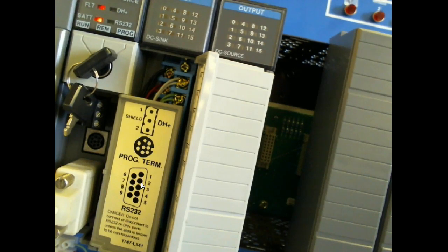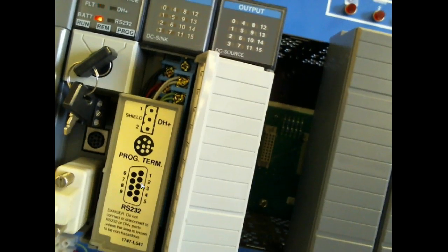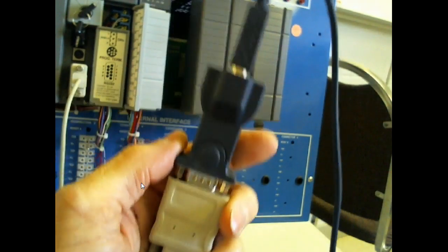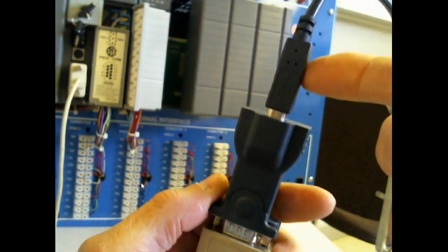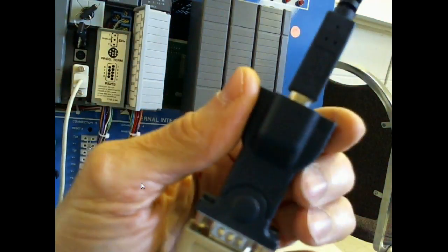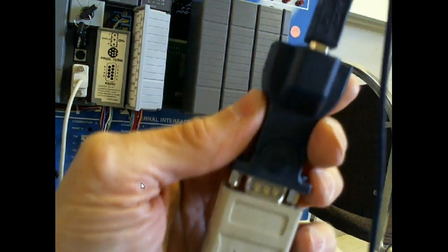Our computers no longer support it, but our serial interface is what we call USB, right? Universal Serial Bus. So we have a special dongle that we buy that takes the USB and converts it over to RS-232. So you'd have to get one of those if you deal with one of these older Allen Bradley PLCs. Just about all your newer PLCs are going to Ethernet. They call it Ethernet IP.